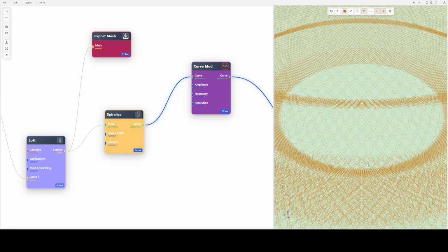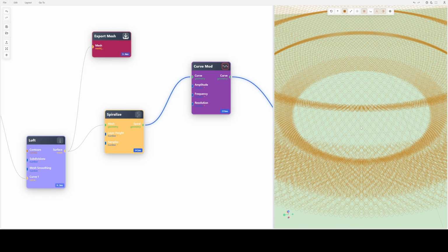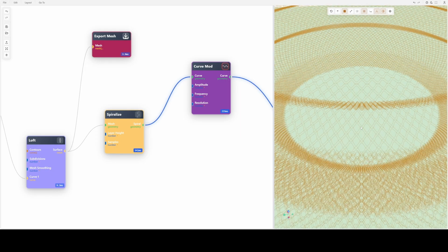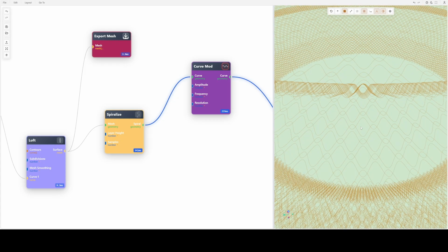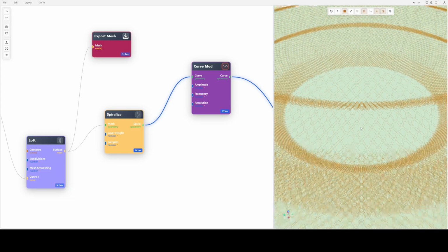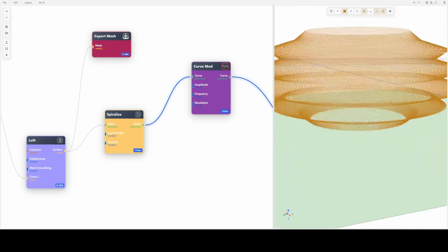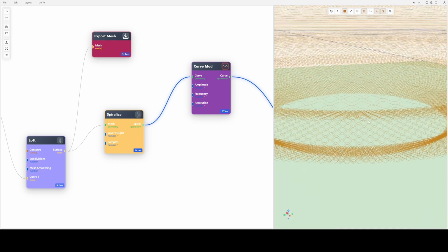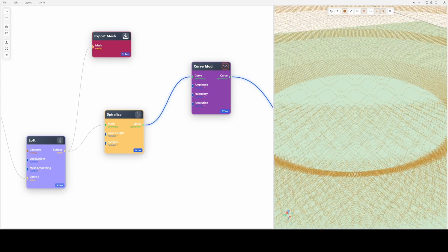But keep in mind, each point will also result in a point in your G-code later on. It will produce a very large G-code, and if you have way too many points, so if the number is extremely large, some printers may struggle with memory for that. So keep in mind, only use the resolution that you actually need, because normally the lines will be smoothed by the filament anyway.